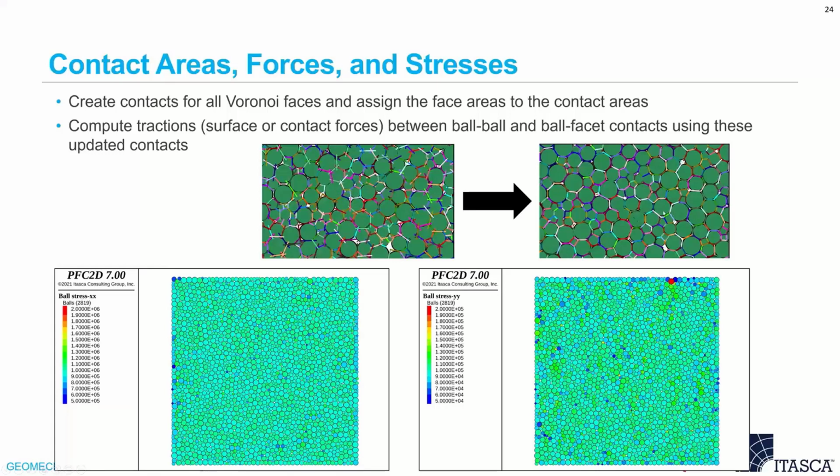And subsequently, if I installed a stress state, which here was, I think, uniform, 1e6 in the x direction and 1e5 in the y direction, you can see that it's not a perfect stress state, but it's quite homogeneous. This is very difficult to achieve in general for packings of granular materials, bonded packings of granular materials. You can also see here that there is a stress deviation, and this can be expected at the boundaries.